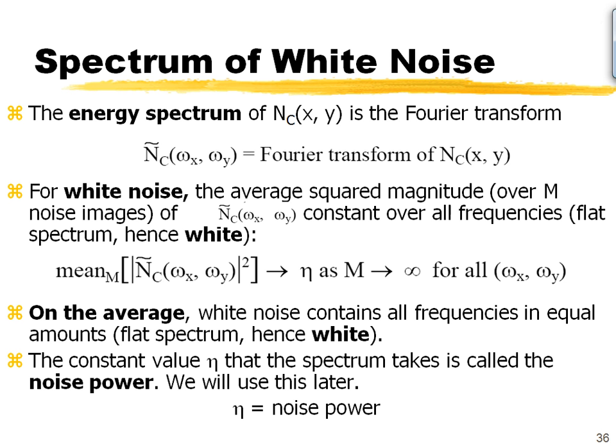I just expressed what noise is. It's a zero mean ergodic signal. Right? So it's a random signal which has a zero mean. What is its Fourier domain going to be? What are the Fourier spectra going to look like? I want to know that. Well, great. If I had n, that's easy, right? I can take the DFT of n and I would be able to see what its Fourier spectrum looks like.